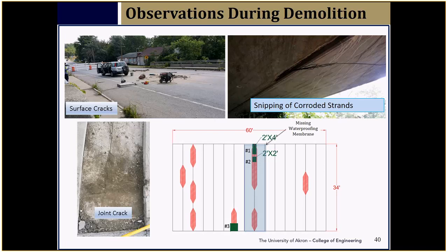To make these changes on a shear key, we're gonna get leaking joints. The probability of leaking joints is substantially reduced if we increase the depth of the shear key. That's the findings from our project.